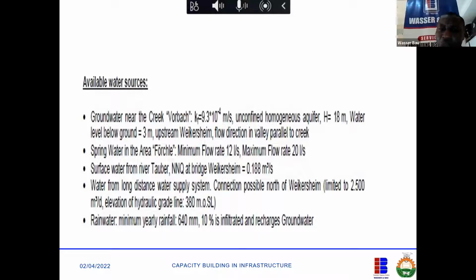I take it again. If surface water contains iron, now I'm just talking about iron. If it contains nitrogen, it comes in form of nitrate. There's a different way to treat it. If it contains sulfur, there's a different way to treat it. If it contains any trace elements, there are different methodologies to treat them. But the simplest one, which occurs 70% of the time, is the one that contains a lot of iron. Iron in form of iron silicates, iron aluminum ion, and any other compound of iron, many of them. The simplest way to treat them is by aeration.